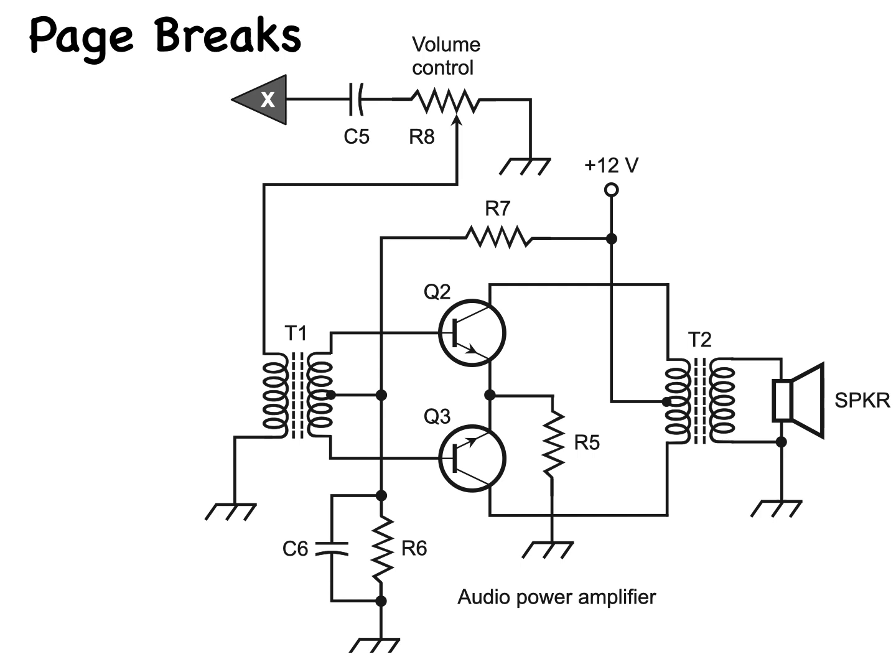In these two figures, the wedge-like arrows represent points meant to connect directly to each other. They take the place of the long, tortuous line in the total drawing. In this case, we need only one set of arrows of this type. Some more complicated circuits need two or more, so we might label them as X, Y, and Z, for example. Then the two X's would connect, the two Y's would connect, and the two Z's would connect.